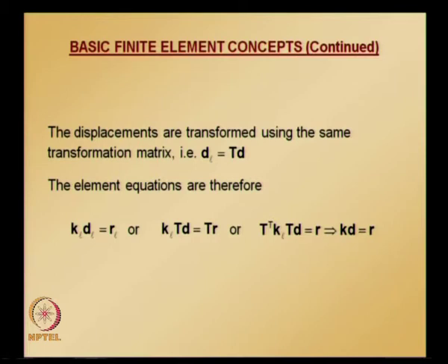Once nodal displacements are known, element quantities such as displacement, axial forces, moments, and shears at any point along an element can be computed using shape functions and their derivatives. For each element, the global displacements must be transformed into local displacements before performing the element level calculations. For an element with uniform load, the equation in terms of local coordinate S, that is S going from 0 to 1, S value is equal to 0 at node 1, S value is equal to 1 at node 2.